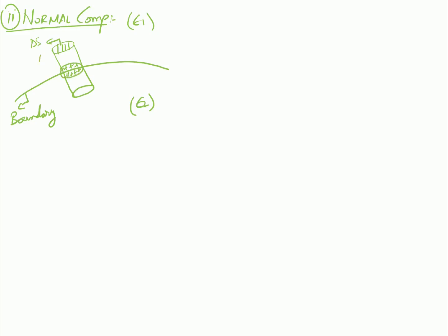Now the height is delta H, but again the height is equal to 0. It's a very small height, and the electric flux density is over here. Its component is over here. So let us call this Dt1. The other will be Dt2. So the Dt2 will be over here. And the normal component is Dn1, and the normal component for this is Dn2. So this is what we are having.